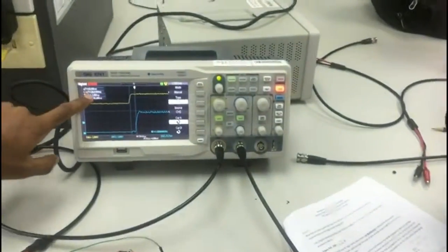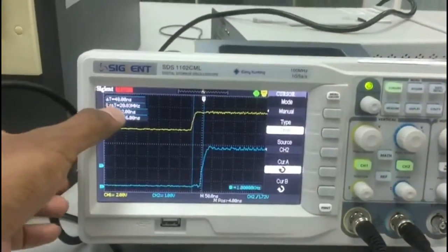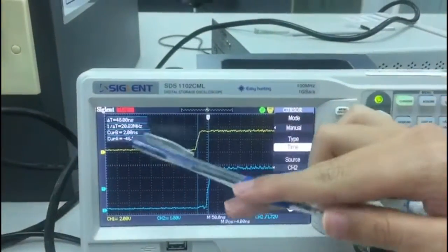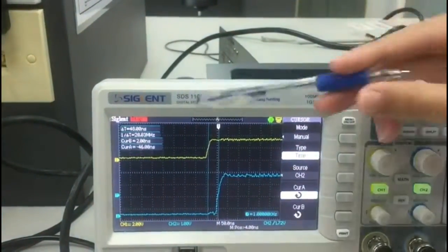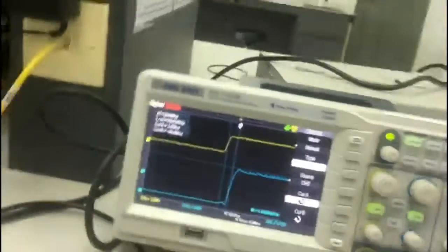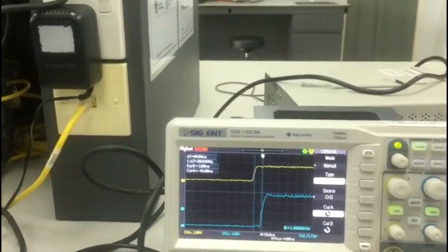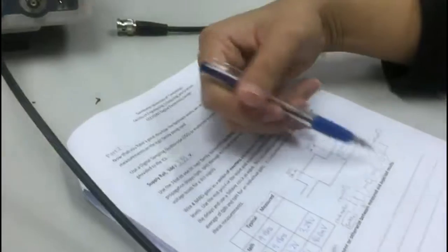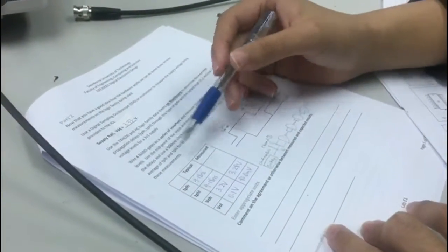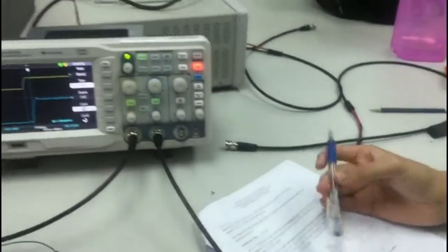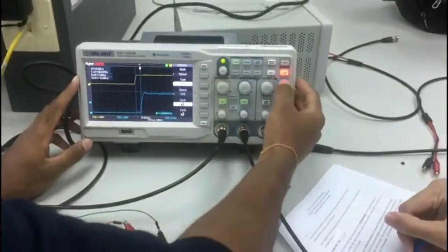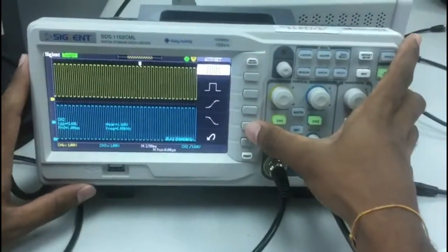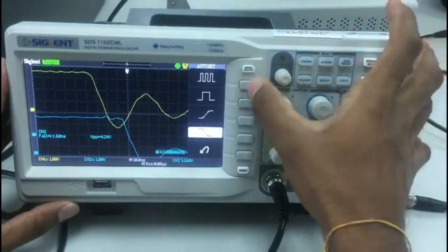So what we get is the measure TPLH, we get 48 ns. So this will be our measured TPLH. And you need to divide by 4 because this whole IC contains 4 NAND gates. So in order to find the TPLH of one NAND gate, you need to divide by 4 to get one TPLH of the NAND gate. Okay, cool, done. So now I will show you how to measure the TPHL from the oscilloscope.